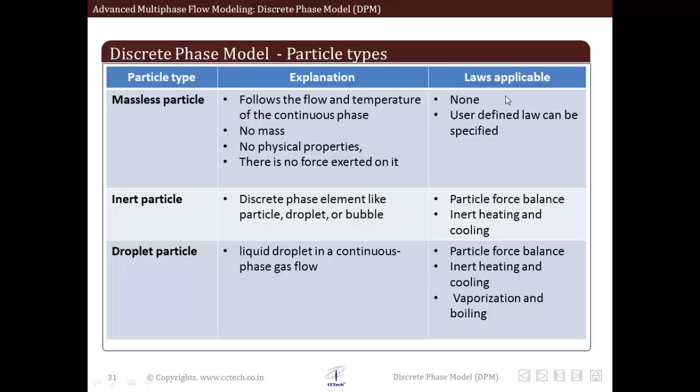Now, what laws are applicable for such type of particles? Basically, there are no laws that are applicable because it is a massless particle without any properties and no forces are exerted on it. So, no laws are applicable, but if we want to include some type of physics, we can always give a user-defined law by UDF.